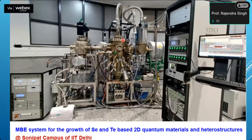This is an ultra high vacuum chamber, and it can go to less than 10 to the power minus 10 millibar. Just think about the vacuum level. It is connected to other chambers. These are the vacuum pumps: a cryo pump, an ion pump, and a titanium sublimation pump, which can take the vacuum down to 10 to the power minus 10.